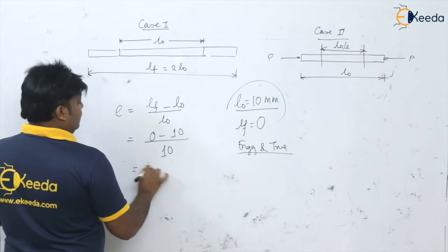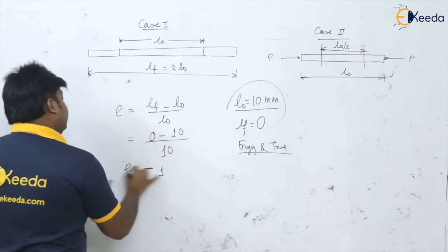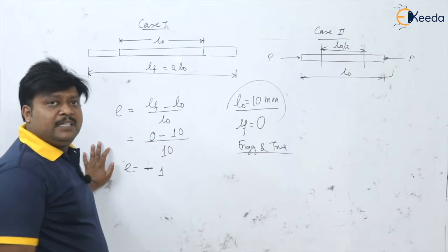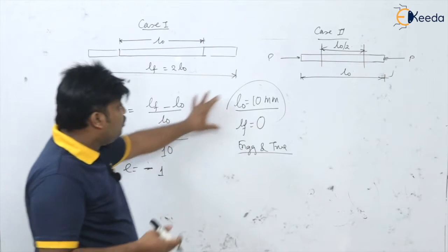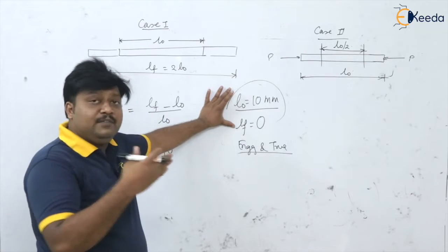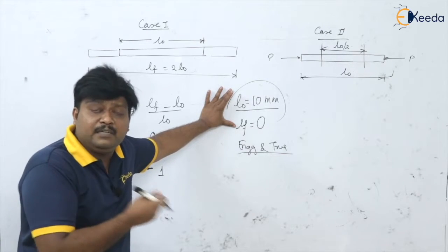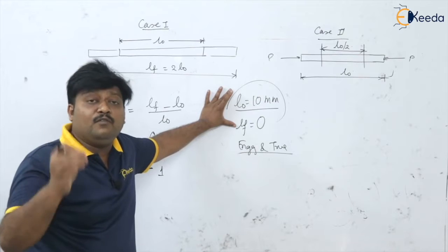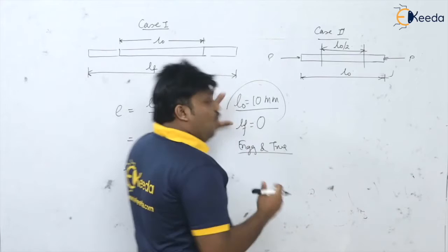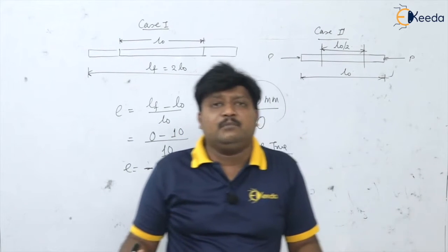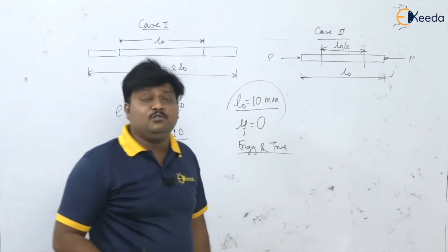Of course, because it's compression, I am reducing it to 0. So negative 1 is my strain. But is this correct? I am deforming the specimen directly from a certain height to no height. Tremendous deformation, a huge amount of working I have done on that material until it comes to 0 height. So let us see how much strain should be induced in the material. Of course it should be infinite. A huge amount of strain should be induced.